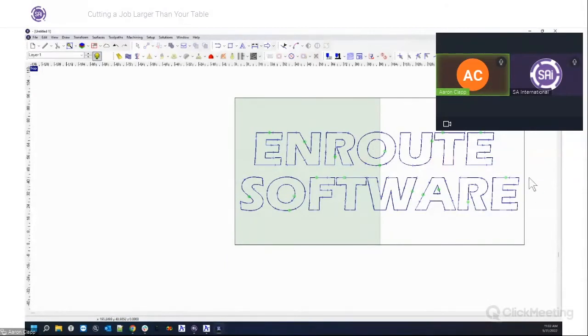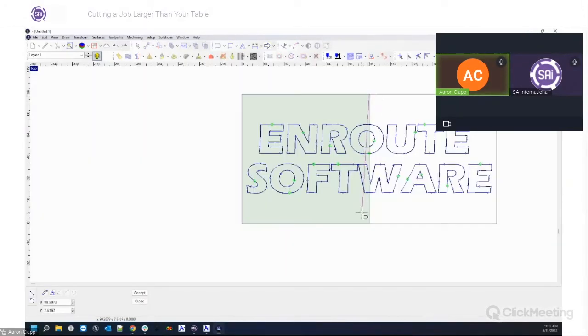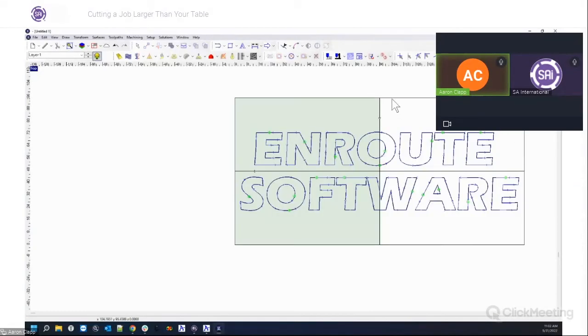And then all I would need to do is draw another line here, and probably another line using, in this particular case, my snap tools. So I'd use the snap to midpoint and then just draw a line here. I could just snap it from there to there, and then from there to there. And then I would just create a perimeter cut on this one, and then just 2 engraved cuts right down the middle.